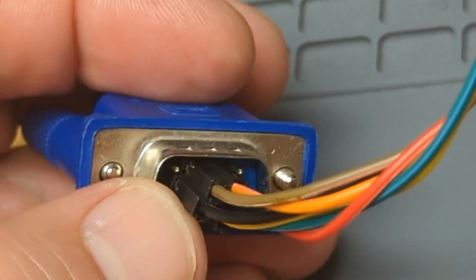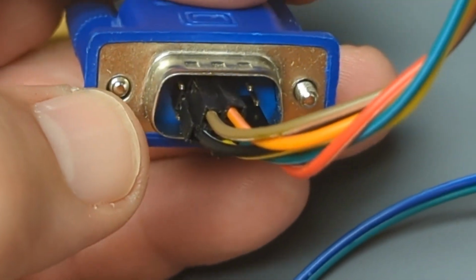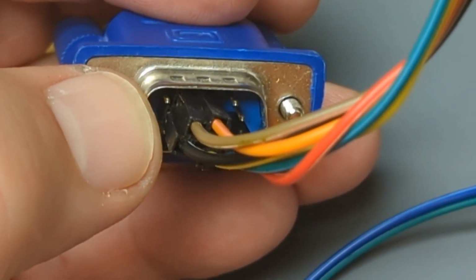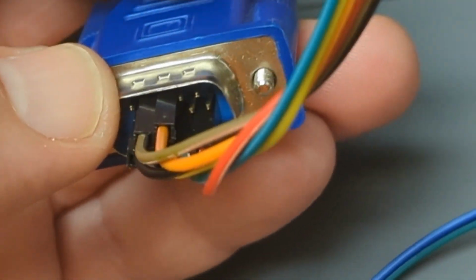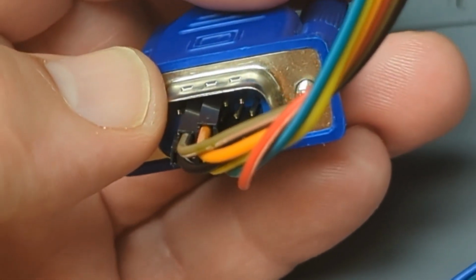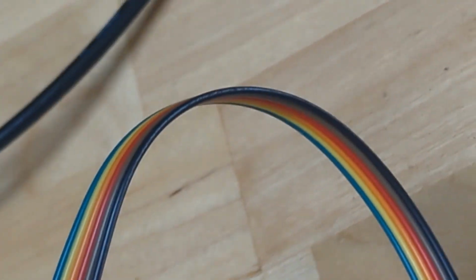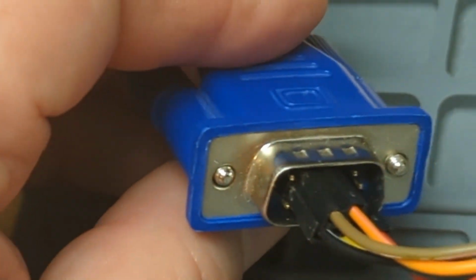That's my ground. And your horizontal and vertical sync are on that top row, the narrow part of the D-sub connector. You skip one pin on the left, you put the two in there like that, and then there should be two that you skip over there on the right on that top row. Okay, so that's where all those pins go. I don't remember which is which. I think the orange one in this case is, what is that one? That's the blue one over here. I'll bet that's the horizontal sync.